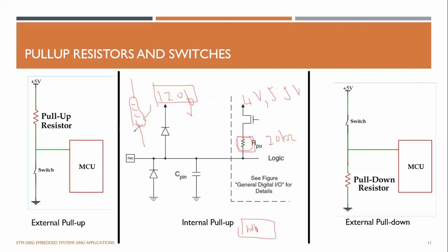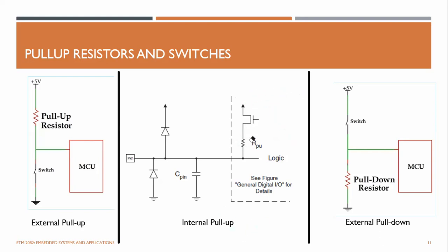It is not something someone has put inside, right? There is no way of doing that. So it is a silicon resistor, and it is voltage independent, but there could be some fluctuations if the chip temperature goes high, the resistance could change slightly. But for many applications, it is acceptable.